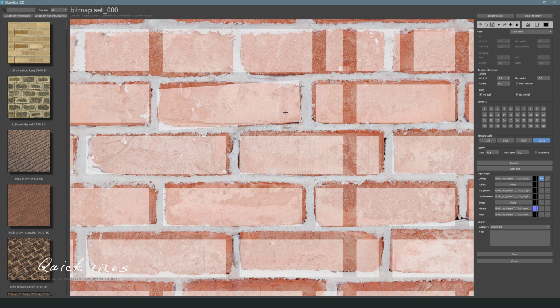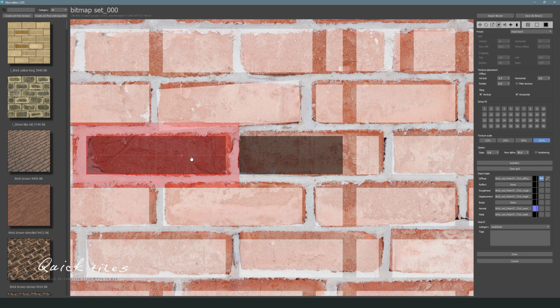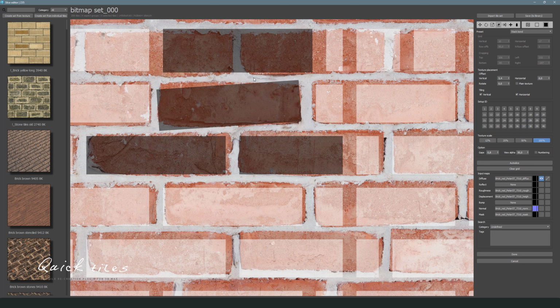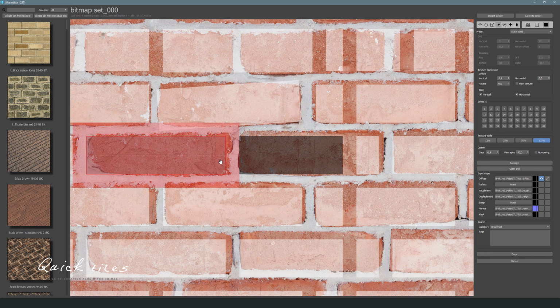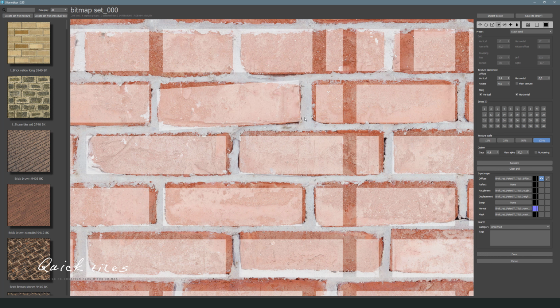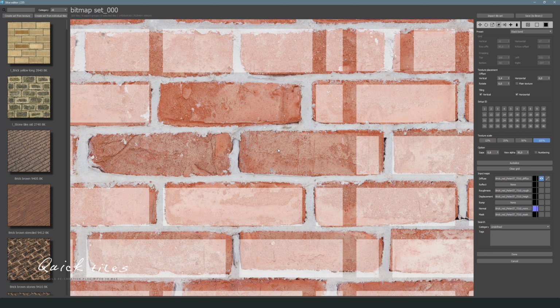The next tool is Eraser. With it, you can remove or disable unnecessary containers. This means that if you have made a large and complex layout, but for some reason you need to temporarily remove some tiles from it, you cannot completely remove them, but simply temporarily turn them off. To do this, click on them with an eraser once. After that, they will become black and will not appear in the final output. If necessary, press the eraser again and the container will turn on again. If something went wrong, the standard Ctrl-Z key combination works in the slicer, which cancels the last action.